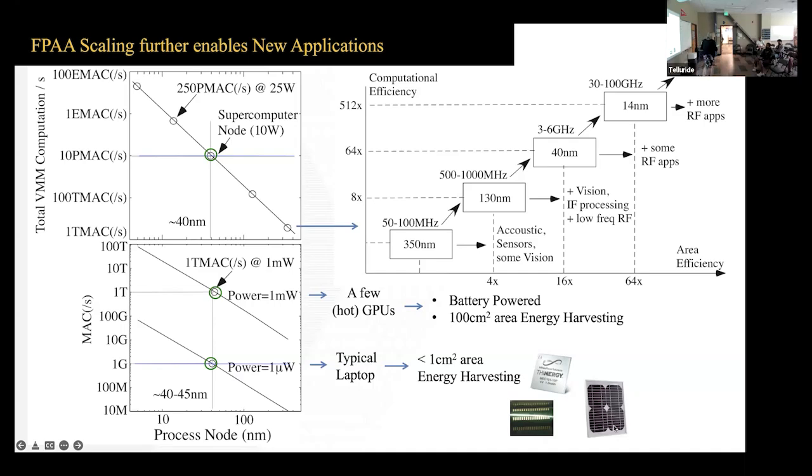It depends on what precision you're calculating. If you're calculating 1 bit versus 8 bits, then you have settling times that limit the frequency. But the numbers are consistent. And the job is not just going to be about power. For those building things at that frequency, you have to build coaxial structures for every wire, so your density goes down. You have to be very careful about how you shield your lines.